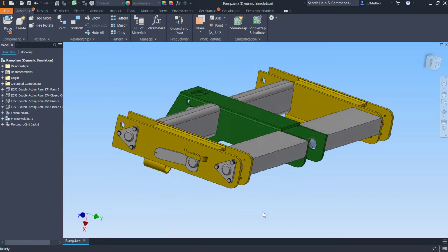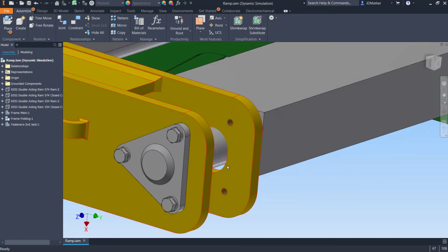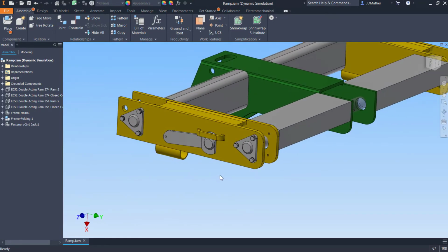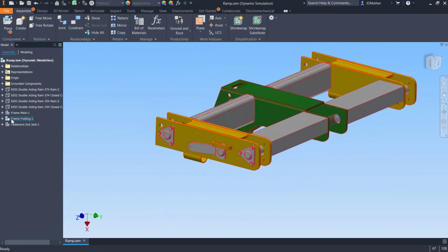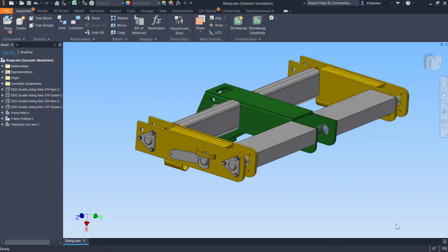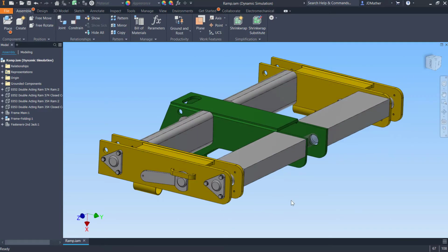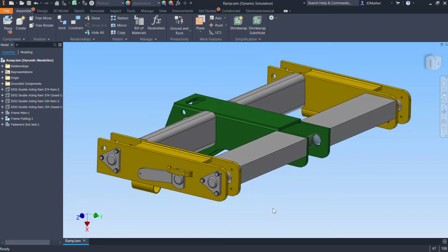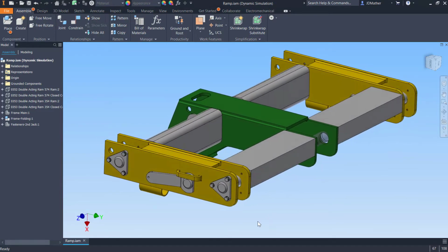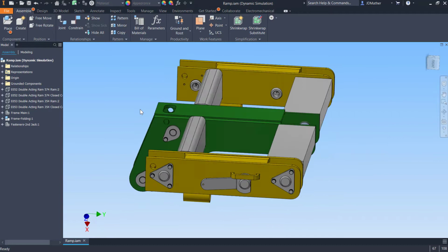Alright, now I want to open up this subassembly because we saw that some of these components aren't in the correct location. So I'll open that and edit that one next. Save often as you're making these changes, and I might save this as revision 1, revision 2, and so forth, so that if you make a major error you can go back to an earlier revision without having to undo everything. So your last correct version you can return to.